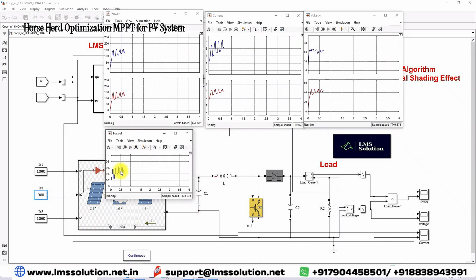The cascade optimization tries to find the optimal duty cycle. The PV power is approaching the maximum point around 160.9, and is maintained around the peak point of 160.9 watts. So for this condition also, the cascade optimization MPPT extracts the maximum power from the PV panel.